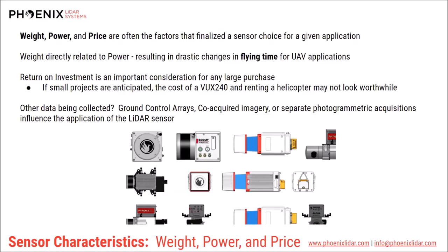The increased weight, the more energy is needed to power the rotors, the UAV, or whatever else is being split between the power, and less energy is left for the sensor operation. This results in lower flying time, shorter flying times, especially when you think about the larger power-hungry sensors that also are fairly heavy.